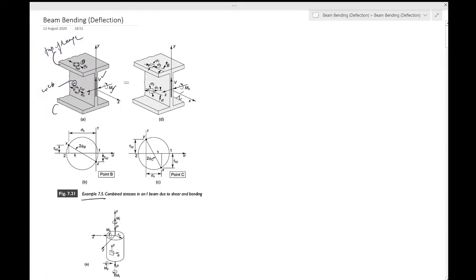A bending stress sigma x is given by 7.16. So that would be equal to minus MB y by Iz, and the shear stress tau xy is given by 7.25. So let's see what 7.25 was over here. That is minus V by Izz times Q, the first moment of area. This is how the shear stress would be. So this was 7.25, this was 7.16.